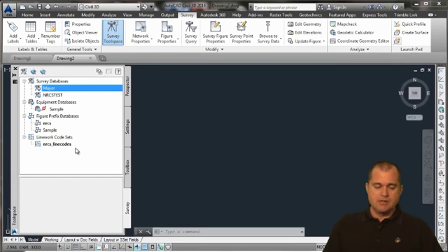And then there's the equipment database, which honestly we don't really use. It is a feature that lets you create a database of your equipment. So if you had a Trimble RTK device and that's the way the survey was created, you could set that equipment up so that when it brings in the data, it identifies that the survey or event was done using that piece of equipment.